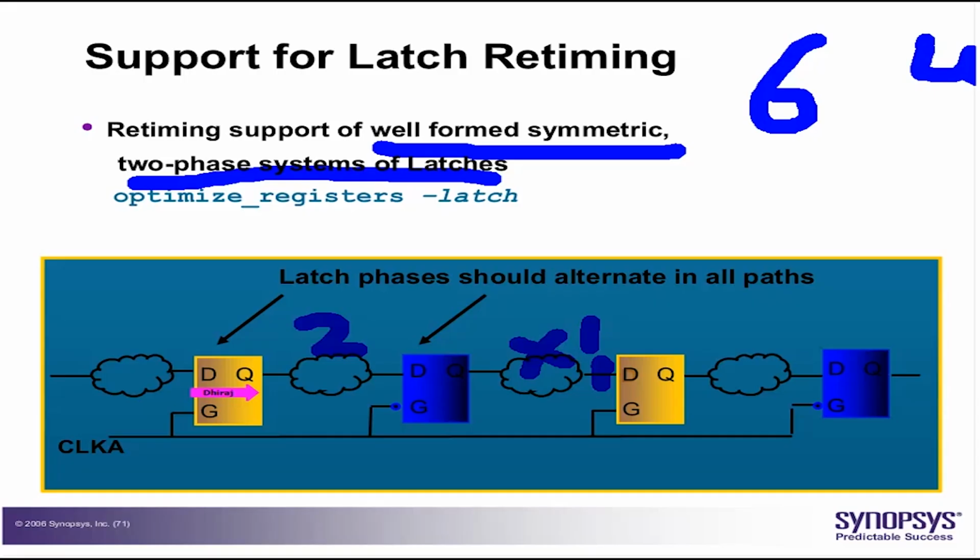So now we are discussing synthesis. In unit 5, static timing analysis, we will assume that a netlist and design are available to us, and see how we time that design properly. In cases where latches are already present in the design, you know nothing about it, you have to make sure that you correctly check the timing. And in such cases, we will see how the timing report looks. It's slightly more complex than a clock to clock report, but we will see how the time borrowing looks. Right? So this is the way it is implemented.